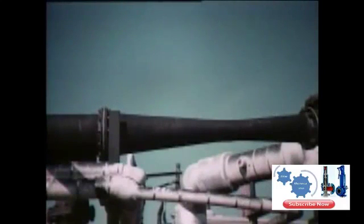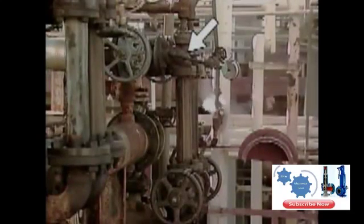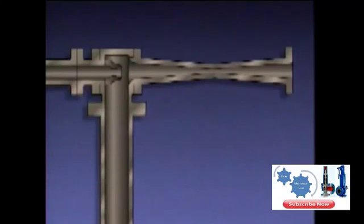Another component that's used in liquid as well as gas and vapor systems is a jet pump. A jet pump uses the flow of one fluid to move another fluid. An air ejector that uses steam to remove air and other non-condensable gases from a condenser is one type of jet pump. There are no moving parts inside a jet pump. Instead, the pump relies on energy conversions to operate.